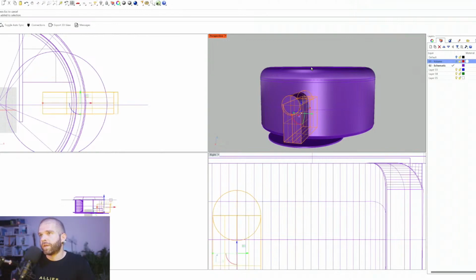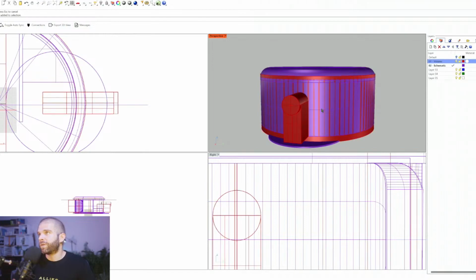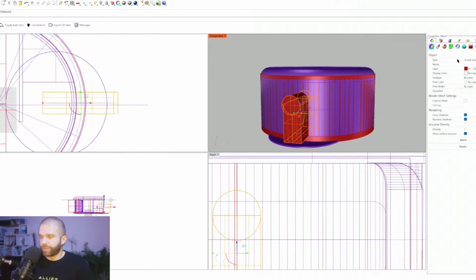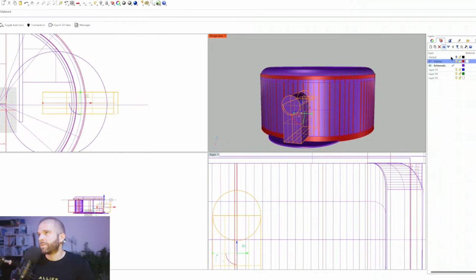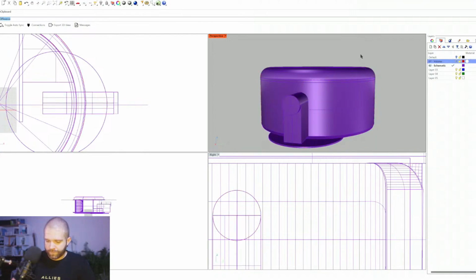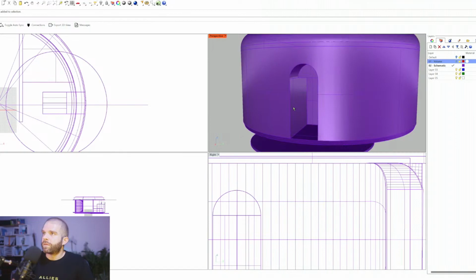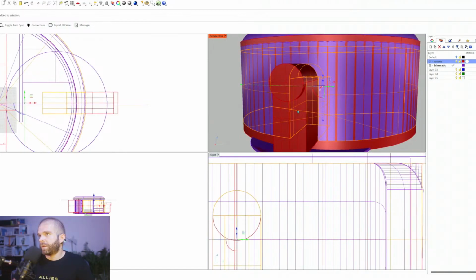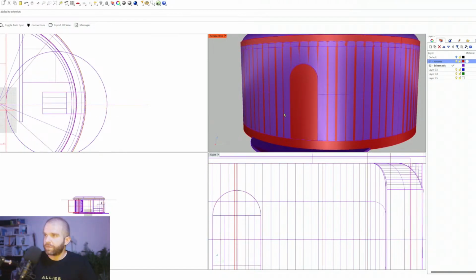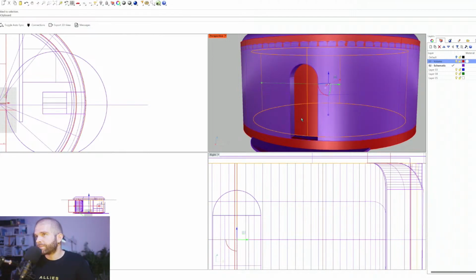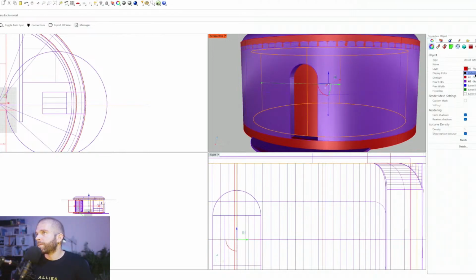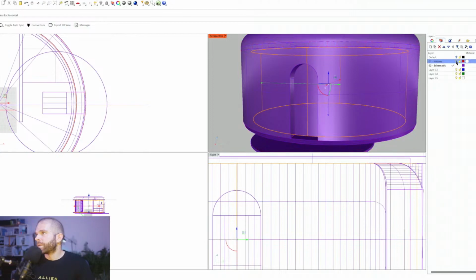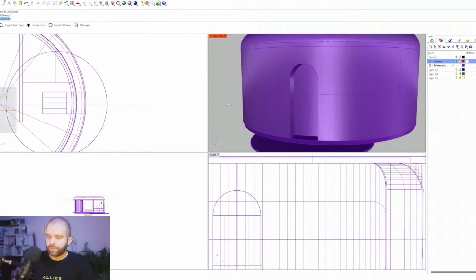And I gotta save this shape, so I'm also gonna send it to layer 1 and then duplicate it back into layer 2. Yes, and our inner cylinder, so that we have an inside space. Boolean difference.